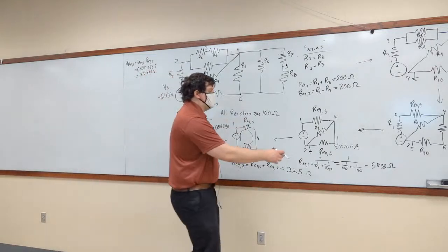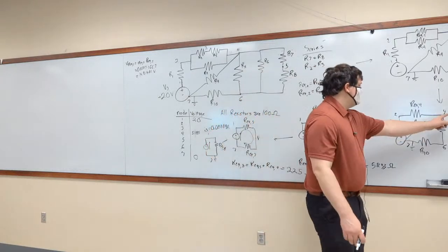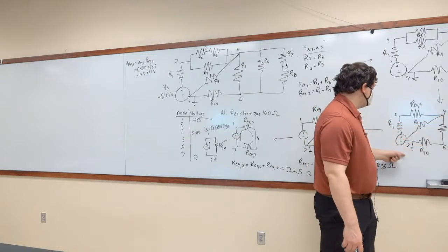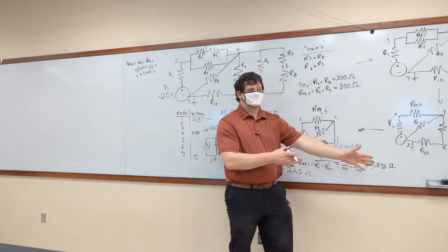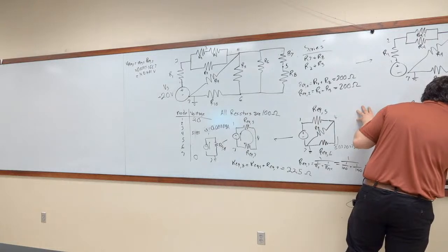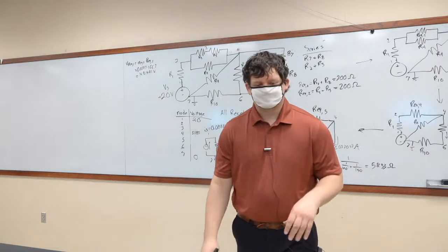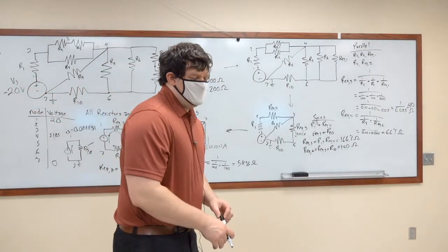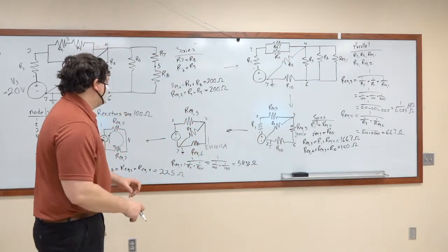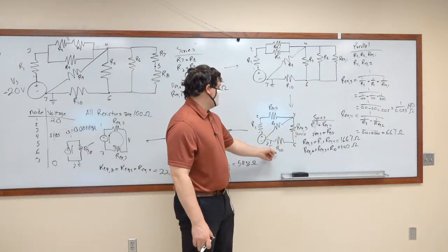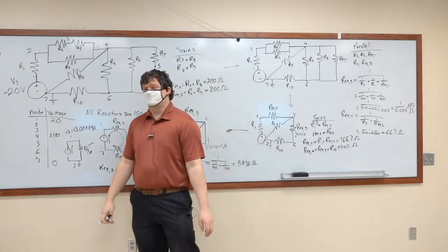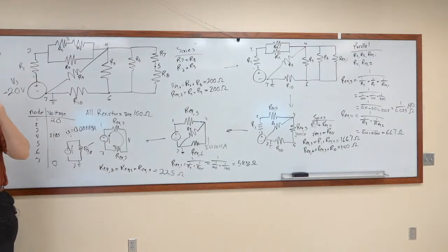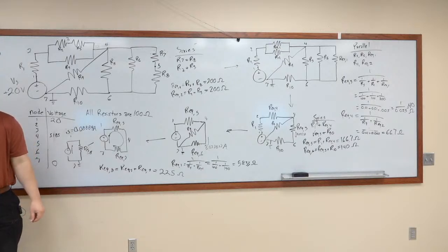So now that I know that the branch going from 4 to 7 is 0.037 amps, we know we have 0.037 amps that goes from 4 to 7 through node 6. We're just stepping back through the system. Having 0.037 amps flowing through that part of the circuit means we can multiply 0.037 by REQ3 or R10 to find what node voltage 6 is. Okay, which one would you rather do, REQ3 or R10? Do REQ3? All right, we'll do it.